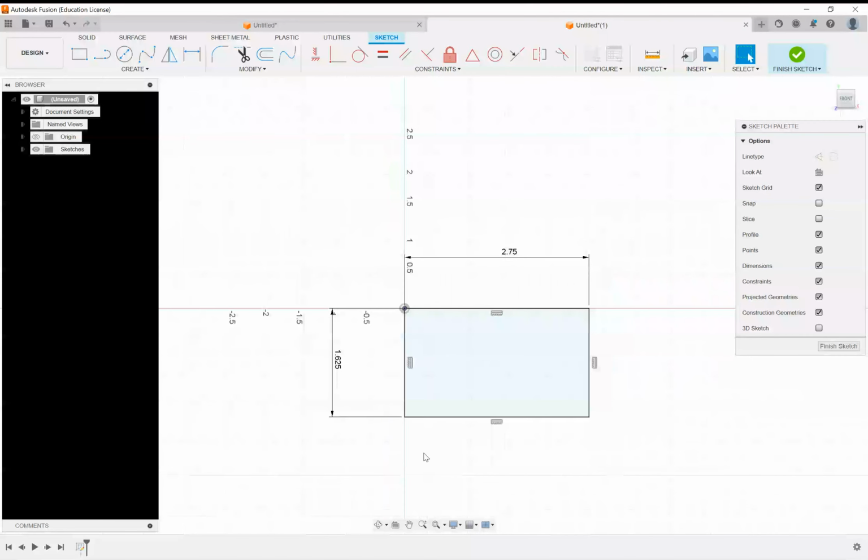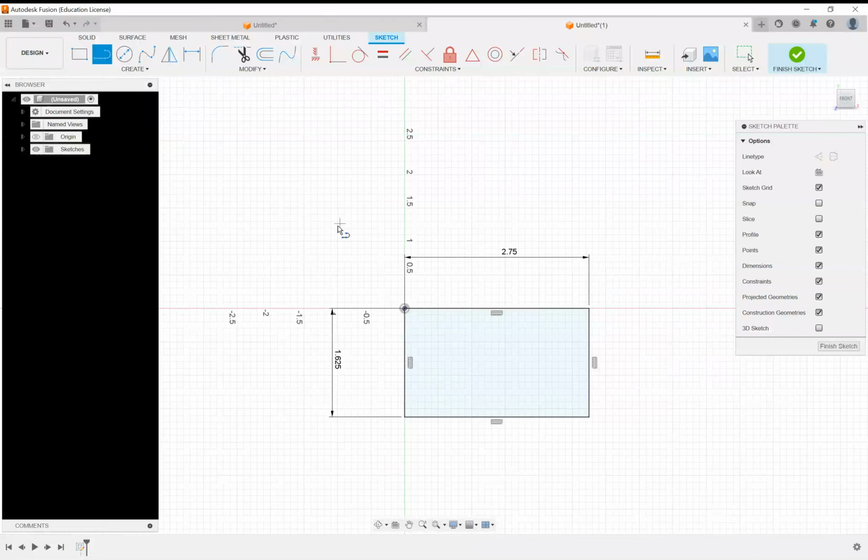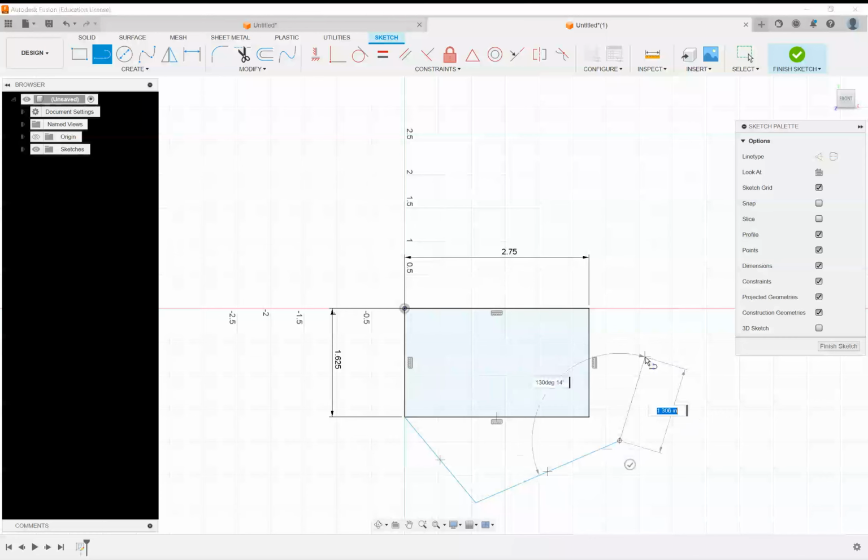All right, so let me show you some other things here, some basic stuff. We can go create lines. All right. I'm going to start from the corner. I'm going to snap to this corner. It doesn't have to, it can be anywhere. It can be this corner. All right, and I'm going to go down and click another point. And it's going to stay in this line creation mode. And I'm just going to click over here and hit Escape.